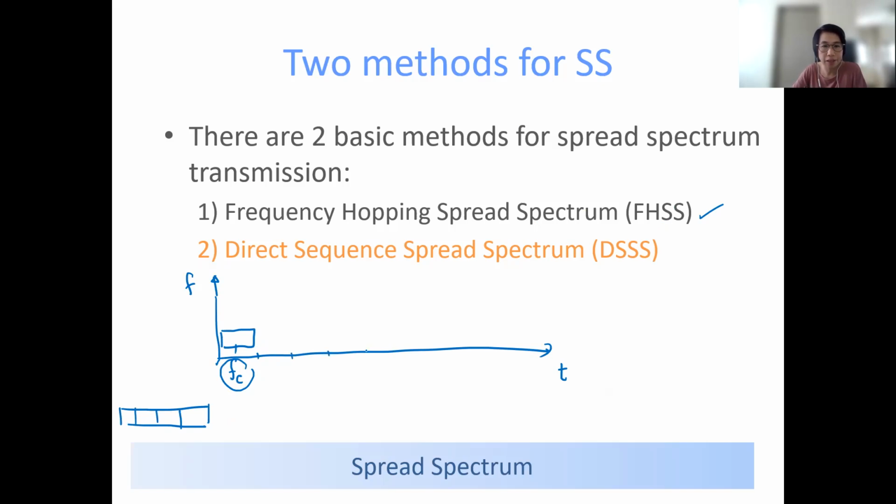you will send the signal as packets, right? Say, for example, this is packet number 1, number 2, number 3, number 4, and each packet will jump to the frequency that has been assigned before at the transmitter side. Say for example, if already modulated with FC, then the frequency shift pattern can be like 4, 2, 1, 3.